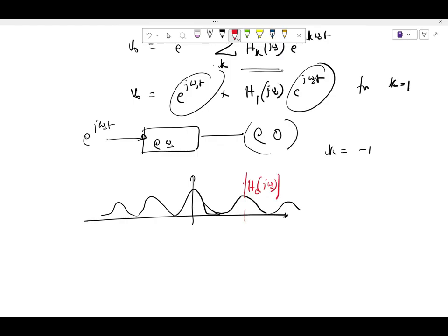If I observe at DC, this is the envelope on the left-hand side of the switch. Be mindful of that fact, right? So it is important to keep track of at what point am I looking at, right? This is the envelope on the left-hand side of the switch. If I look at the envelope on the left-hand side of the switch and I observe the value at omega s,